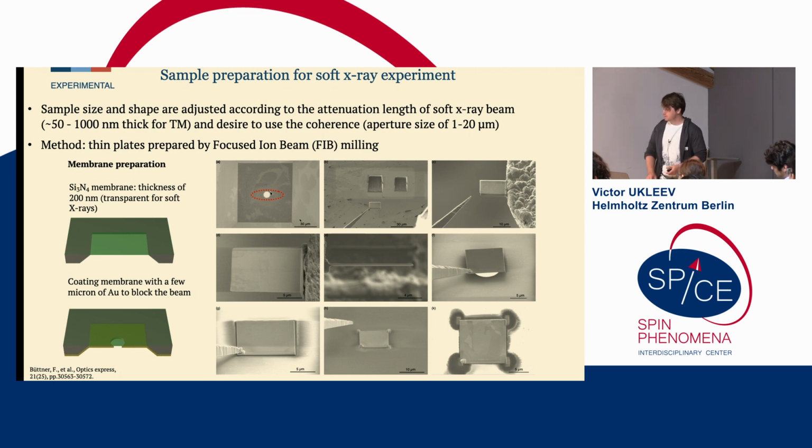We want to avoid that, so we use this kind of aperture. Then we take our single crystal material and make trenches with the gallium ion beam. We pick it up using a micromanipulator and put it on a copper grid. Then we further use a weaker gallium beam to thin it down to 100 nanometers or so.